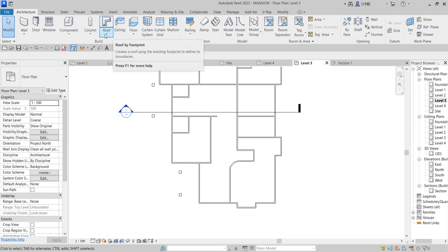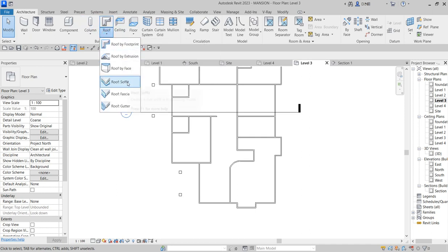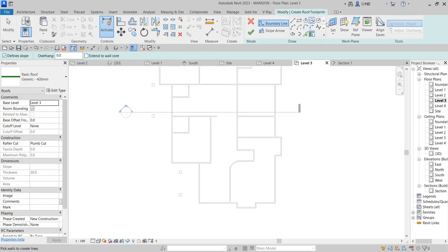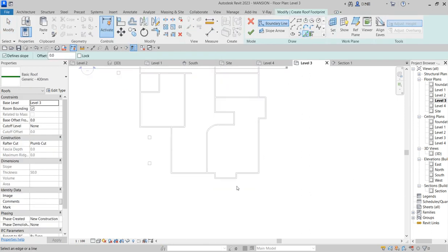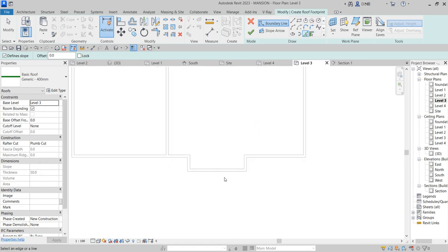So we want to lift the roof up above the normal something we used to see. So you click on this and say roof by footprint. Roof by footprint will do the same work we used to do by creating this, then from the offset. From here, the first thing to do is look at anything that's having issues, and you don't bother yourself with that for now. Then you click on 600, then you start drawing.